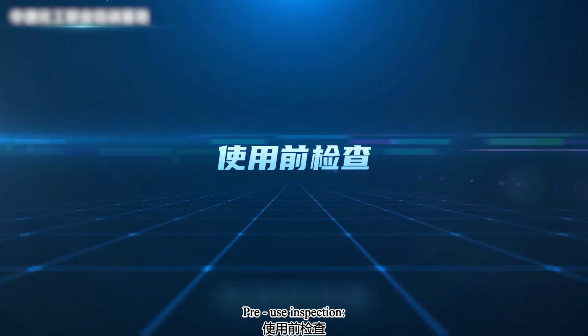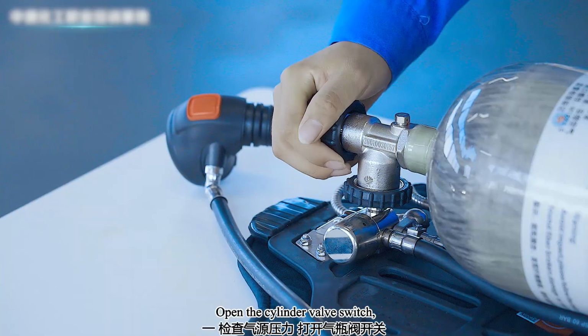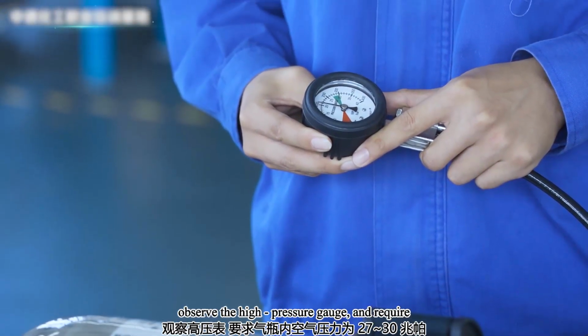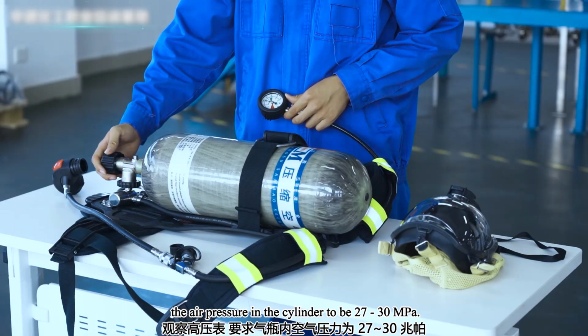Pre-use inspection. First, check the air source pressure. Open the cylinder valve switch. Observe the high pressure gauge and require the air pressure in the cylinder to be 27 to 30 megapascals.